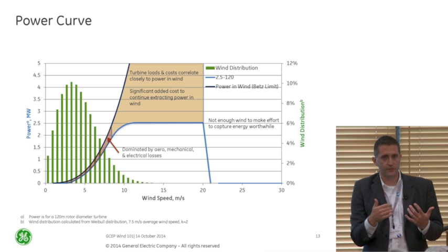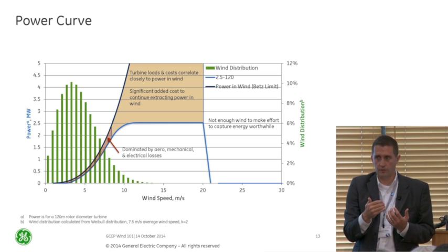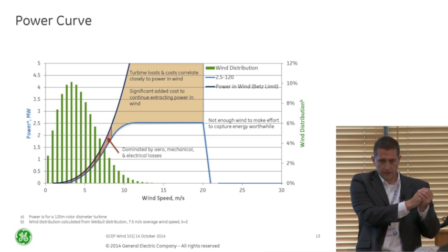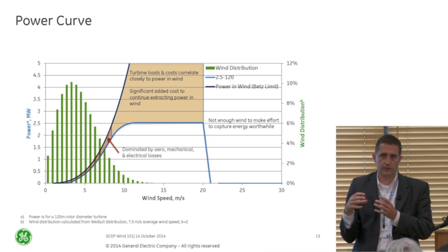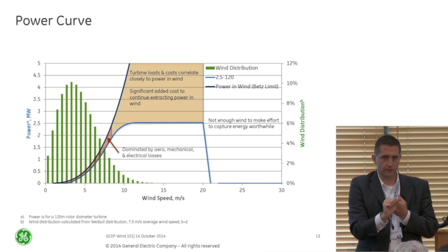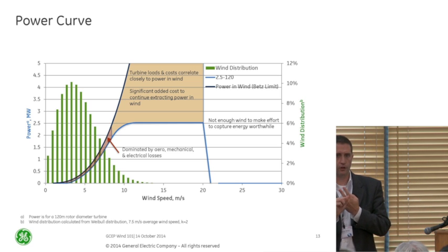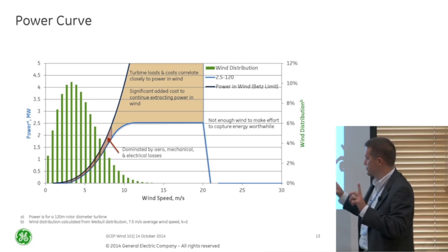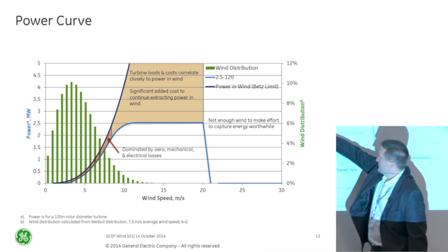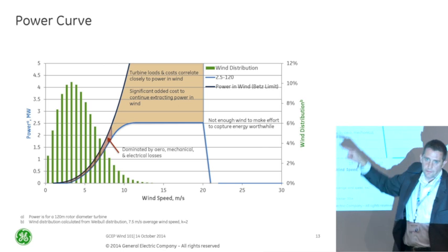It's also some losses in terms of the electrical efficiency of taking that rotational speed and transmitting it into electricity. So that's your gearbox losses, your generator losses, your converter losses, whatever collection losses you might have going out of the turbine. So you see a little bit of reduction there. But the interesting thing is that it stops. It stops and cuts off here, right?